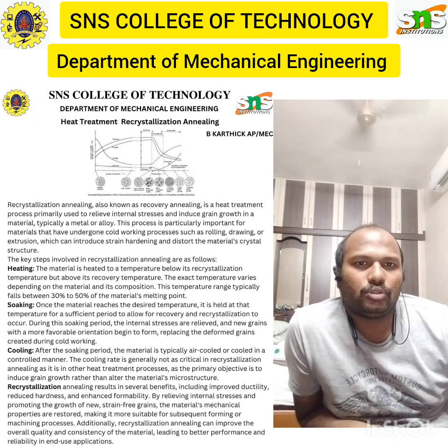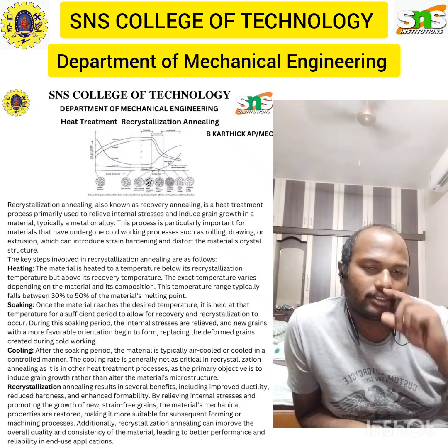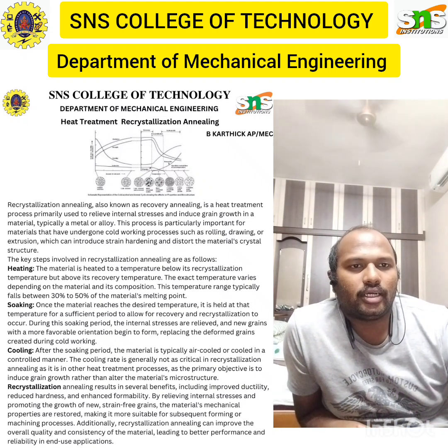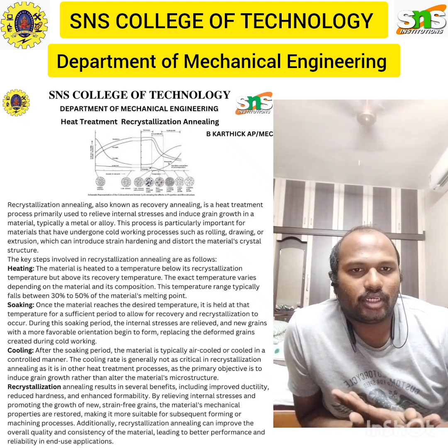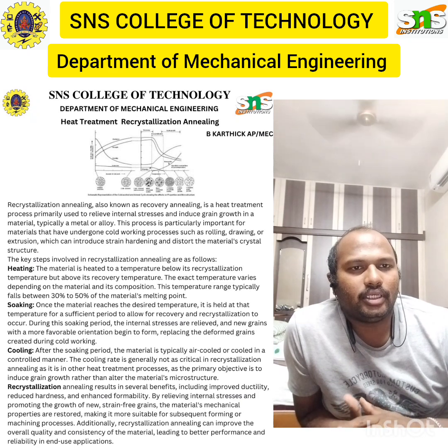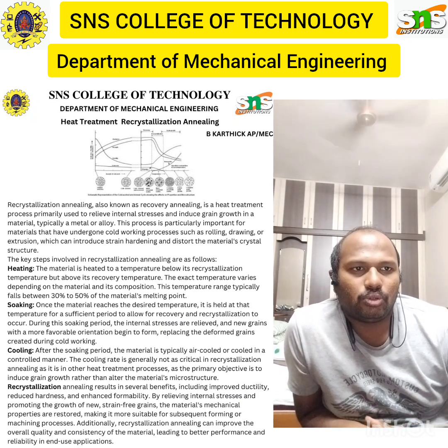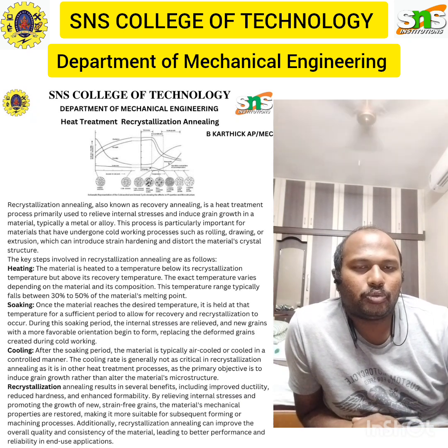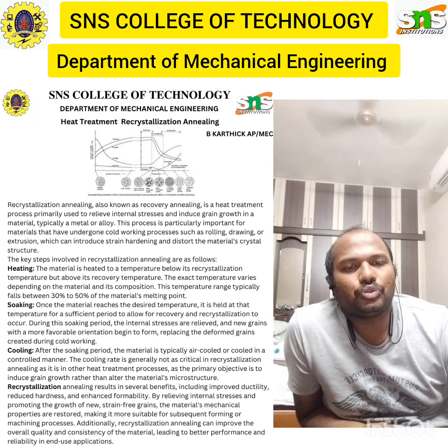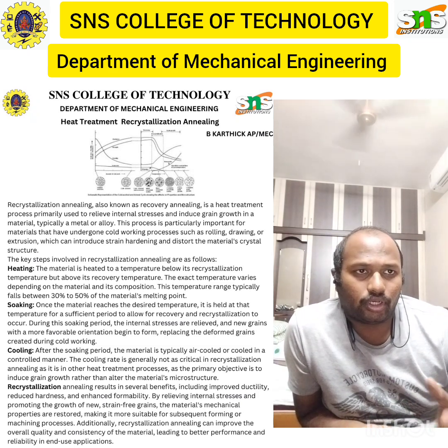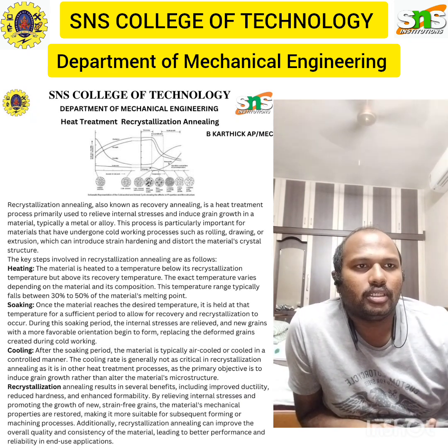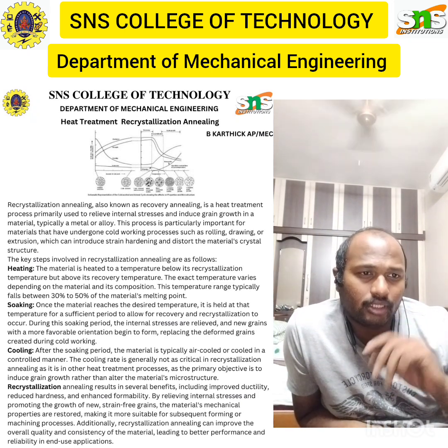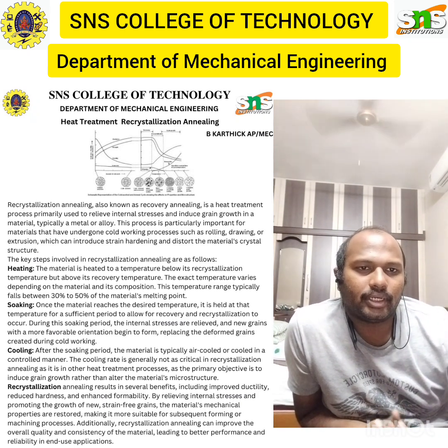So due to this reduction in hardness, the material is softened and it can be easily machined. So the main objective of this spheroidizing is to improve the machinability and also the formability of the particular material, so that the material can be easily machined.